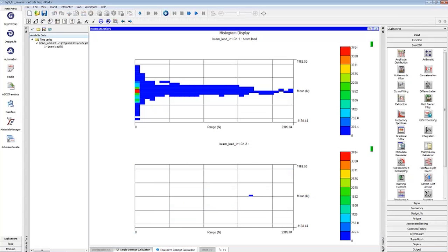So the test cycle that I created had an amplitude of 850. Okay, so that's a range of 1,700. Range is nothing more than just double the amplitude. You can see this amplitude here falls at about maybe 75% of the way up to the maximum amplitude seen in our test, or in our infield loading.